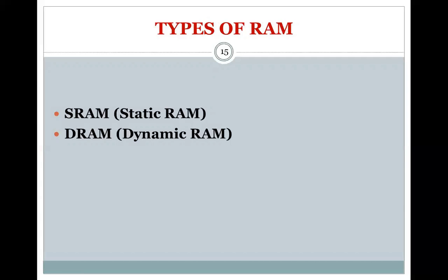They are meant for reinforcing the data which is written. Because of the reinforcement, the data will be present till the data is taken out in terms of a read operation. So when you read, you get without violation the data you have written. That is why static RAM is named so.